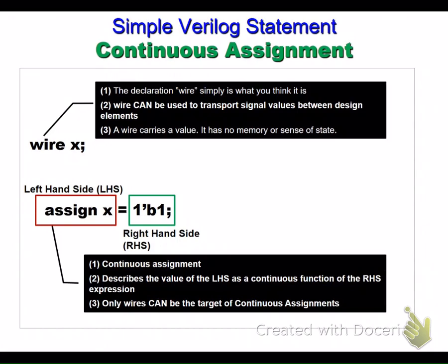a simple syntax in Verilog. Assuming that I have a certain output, or a certain signal, let's say that way, that I would like to assign a value to. So I would like to say, assign to that particular signal x a certain value. We'll understand in a minute what that value is, but I just would like to assign a value. Before I can assign a value to this, I have to define x as something. In that case, if I'm using an assign, I have to define it as a wire. So I will define it as wire x, semicolon, before I use the assign statement.